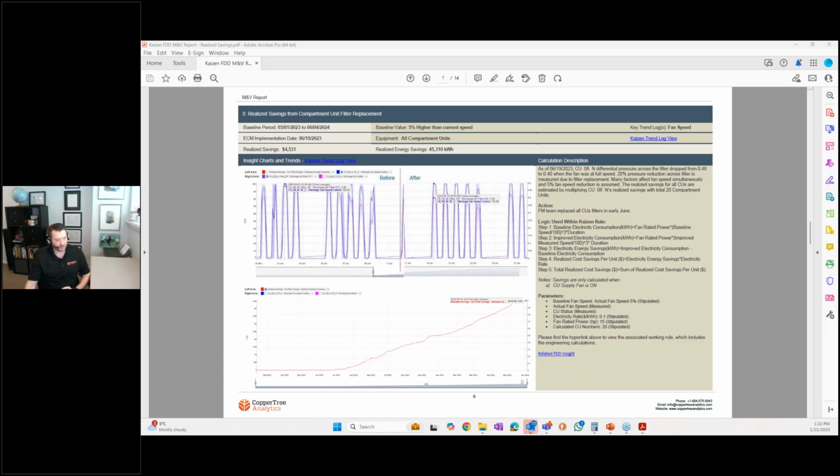For that last case study with 20, we already talked about that. Let's see, any other devices required besides K-Link and KCOM if we have existing Kaizen, BACnet, and BMS already installed? No, that is the only device. If you have Kaizen already, then we already have the data from the read portion. We pretty much just need to add KCOM to be able to do the two-way interactivity with the BAS. So we wouldn't necessarily need to put a K-Link in place if you already have the BACnet communication coming to Kaizen. If you don't have that, or we want to update it, maybe with a copper cube, we could deploy that in parallel for a while and then phase out the other system you're using for collection.